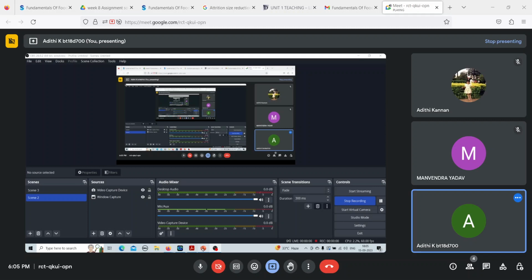So this is the definition of work index. So this entire term goes to 0 and you have 2C is equal to root of 0.1 into Wi. So this is the relation between your Bond's law constant and your work index. So now that work index is given in the question, you can calculate what is 2C and you can substitute back inside the equation.